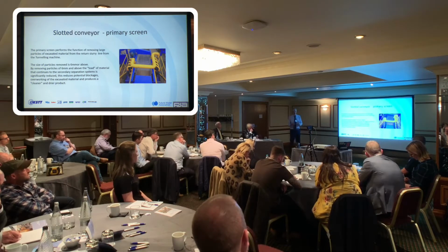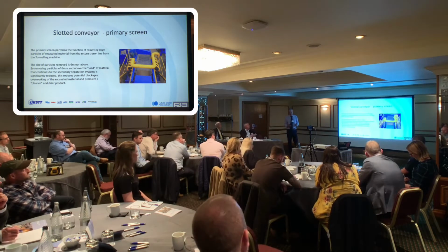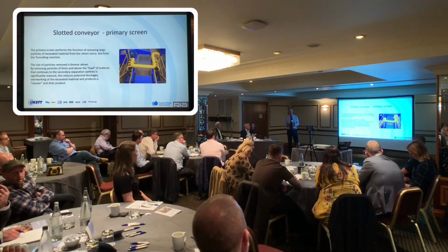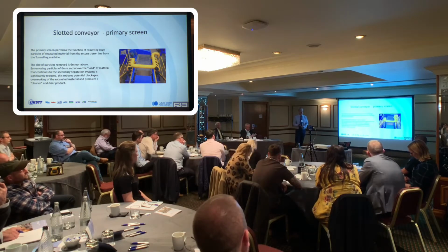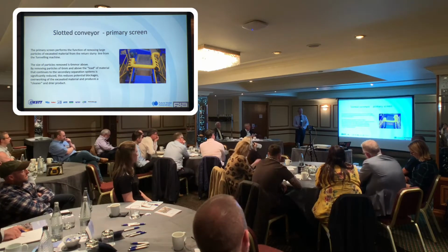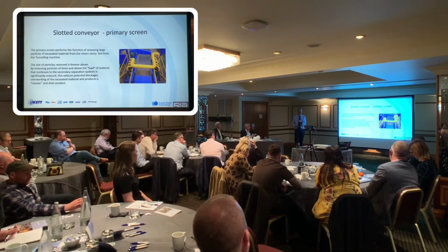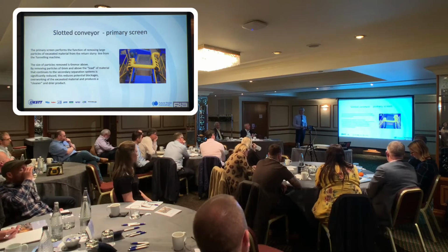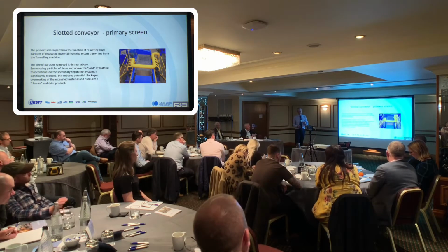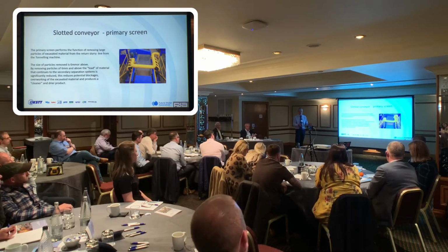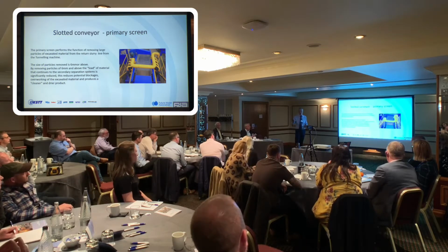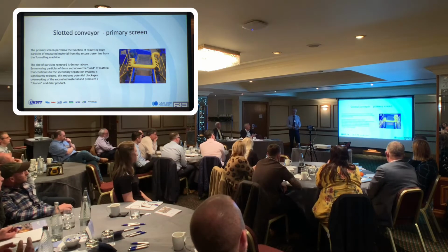Dependent on the ground that you're in, different grounds break down in different ways. So granular soil will not break down very much, so sands, gravels won't break down much, other than they may be crushed within the machine if there's a maximum passing size at the back of the screen. But then when you get into cohesive soils and silts, you could in some circumstances have 100% of the excavated material, white chalk, in suspension in very, very small particles, and that's very difficult to deal with.